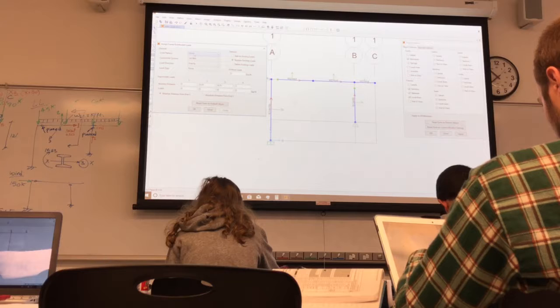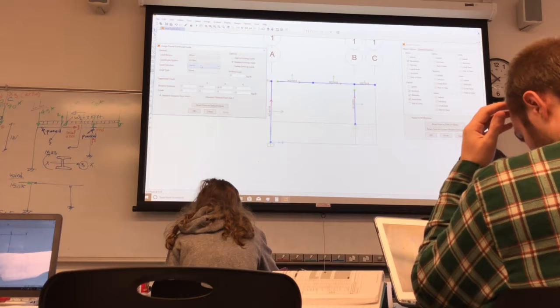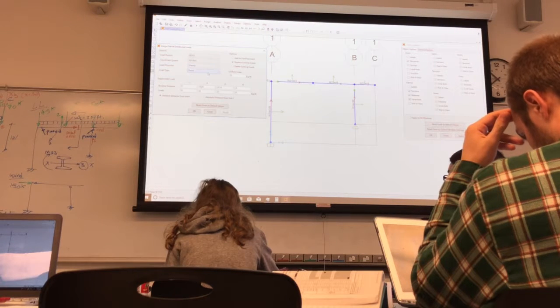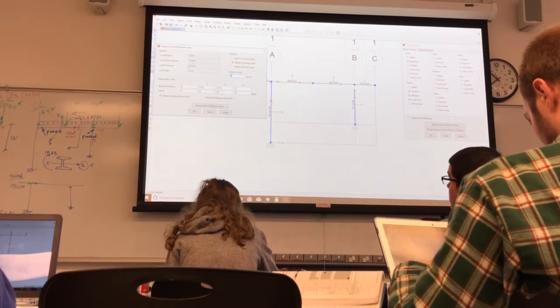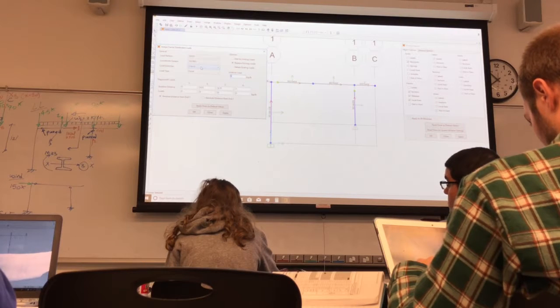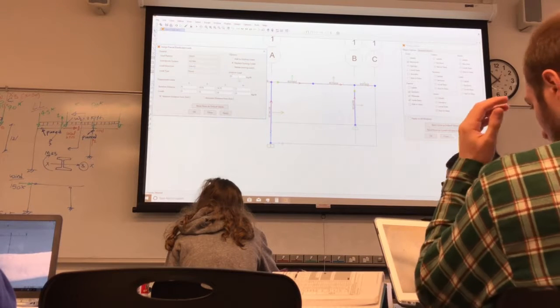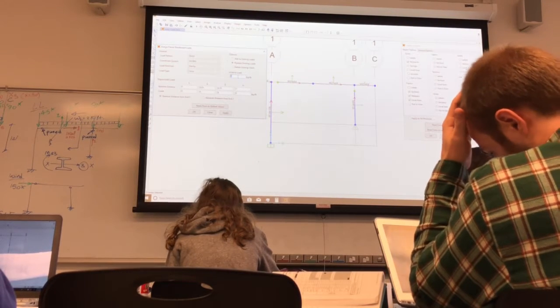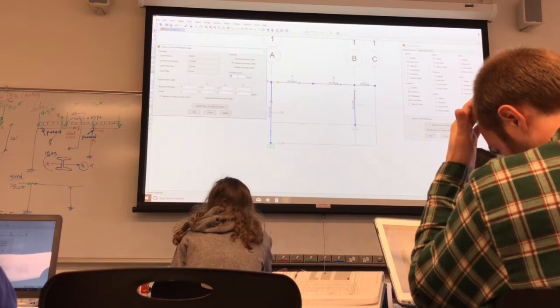So that load, that's the first thing. Gravity, so that means in the negative direction, negative Z, and it's force, and I have a uniform load. So I have to select all these beams and apply a uniform load. It already defines it as gravity, so I don't have to put a negative sign. That's why I like this option. But you have distributed load in X, Y, Z, and so on, but usually uniform loads are distributed in gravity. So that's 3 kip foot.